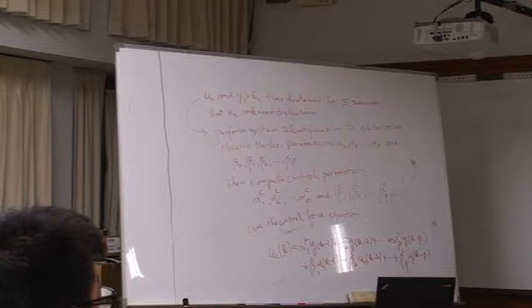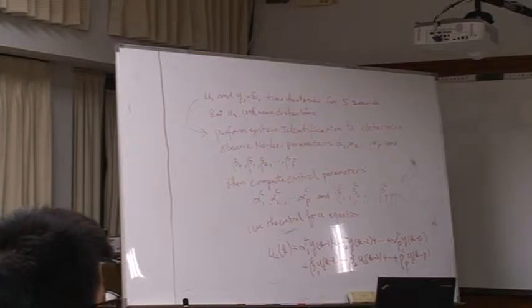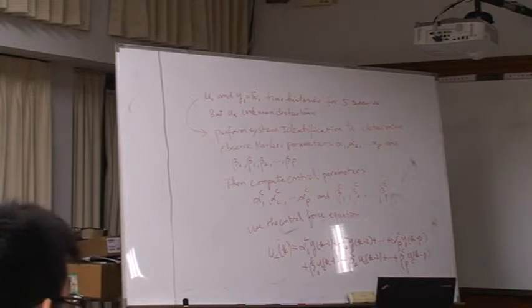That means generalized predictive control is off because I need some data for system ID. So the 0.6 second data I use for system ID, but I have less than 0.1 second to do all the computation.